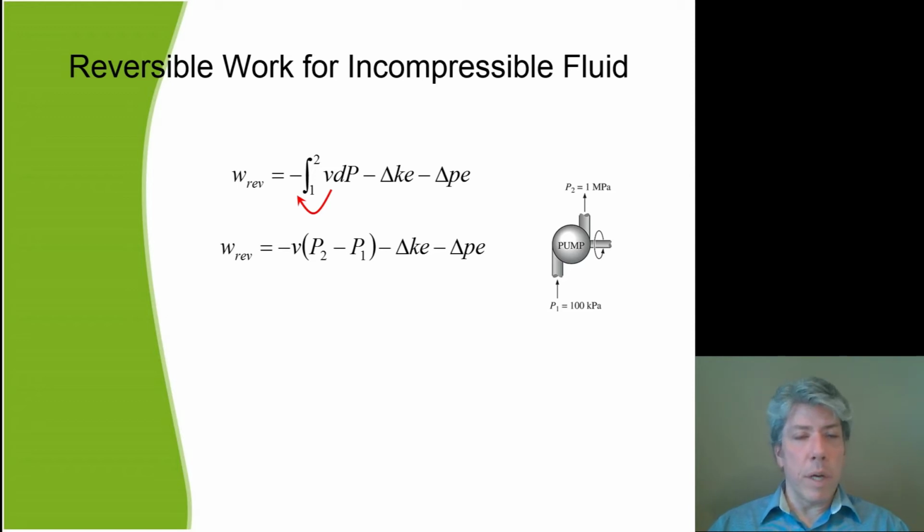But this is an equation you've probably dealt with. You may not recognize it yet, though, because in most fluids classes you deal with density, or more usually specific weight, where specific weight is the acceleration of gravity multiplied by density. But think with me for a minute. The specific volume is just the inverse of density. So have you ever seen a delta P over rho type term in any of your fluids classes, or perhaps a delta P over gamma, where gamma is the specific weight, or in other words the acceleration of gravity multiplied by density? We're actually playing with something you've probably seen before.